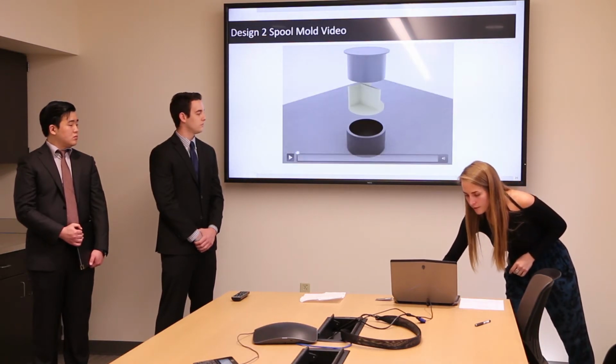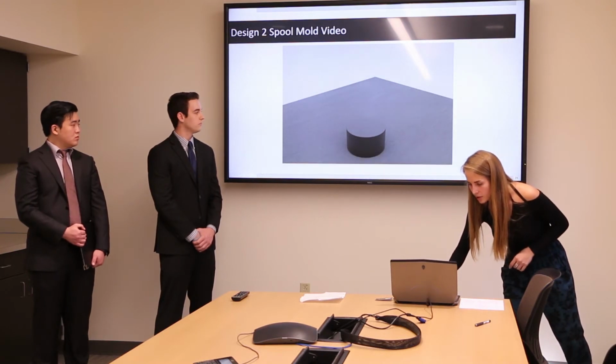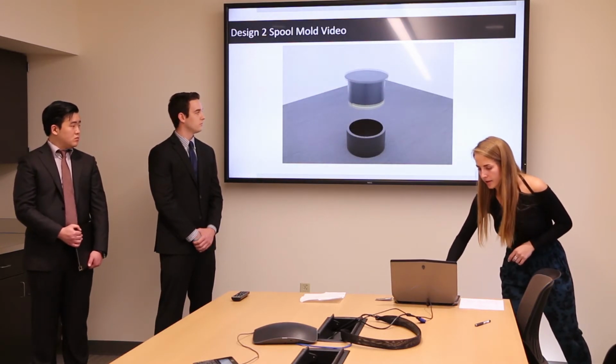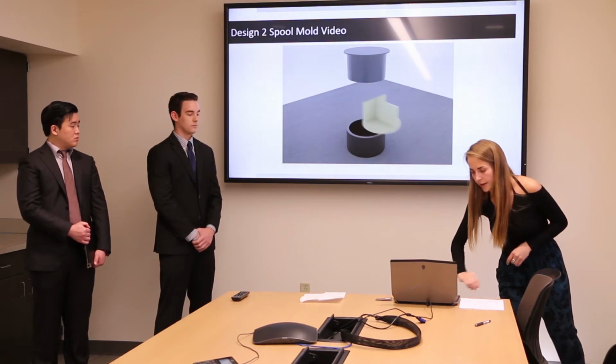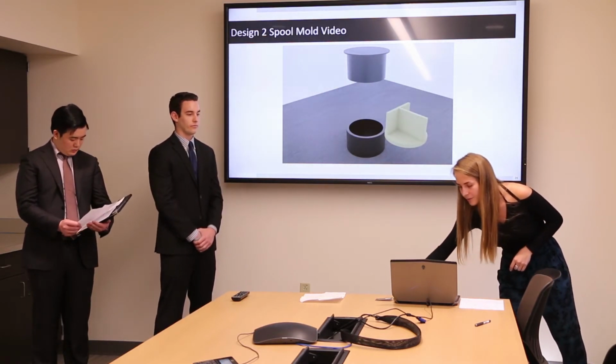This is a video of the spool mold showing how side A comes down on top of side B, the material will be injected, and then it will come up and the ejector pins will push out the finished plastic mold, or the finished plastic spool.